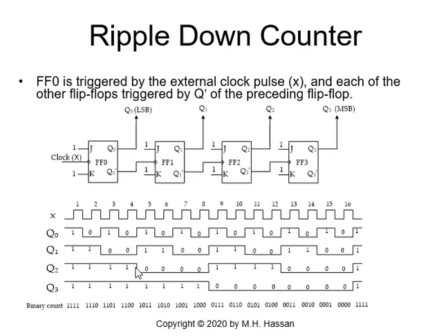You will trigger flip-flop 2. And at the positive edge of Q2, you will trigger flip-flop 3. So all of the flip-flops are negative edge triggered, since we are taking the clock from Q0 prime, and we are looking at the complement of Q0 prime, which is Q0. So you see the triggering here at the negative edge of Q0 prime, which is the positive edge of Q0.